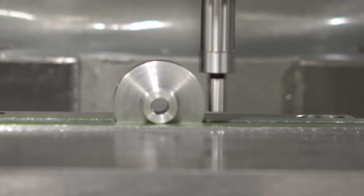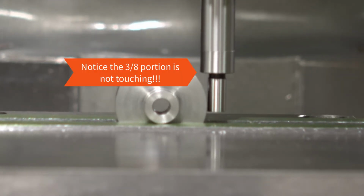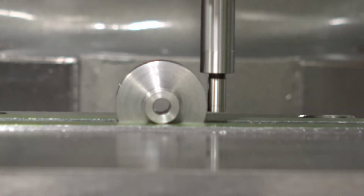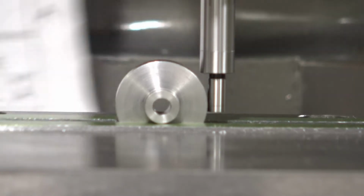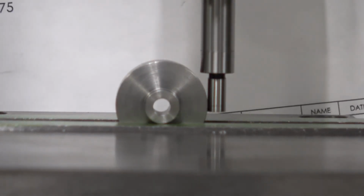Now your perspective is not going to be the best one to see your edge finder kick out. You're going to be 90 degrees from where your perspective is. So we're gonna come nice and slow till it kicks out. And we wanna make sure that that 200 thousandths diameter is the only thing that's touching the 1-inch diameter cylinder. And it looks to be that's where we're at right now. So we're gonna set our dial to 0.